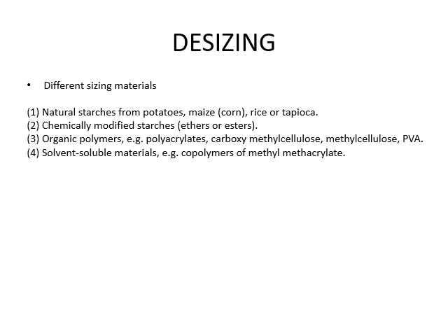Synthetic sizing materials such as PVA, polyvinyl alcohol, or CMC, carboxymethyl cellulose, or PAA, polyacrylic acids, are normally water soluble. These materials can usually be easily removed by using a warm water or even hot wash, which includes detergents and alkali. The specifics of the time and temperature of processing mainly depend on the exact nature of the synthetic material and the amount of it that is present.